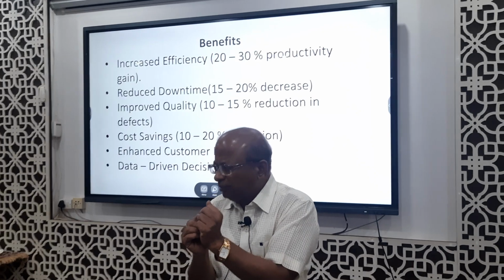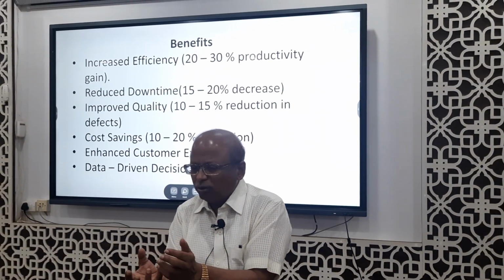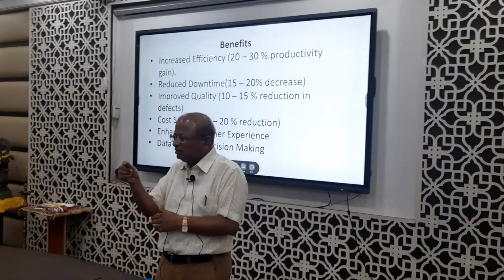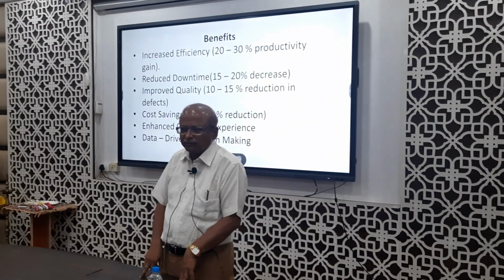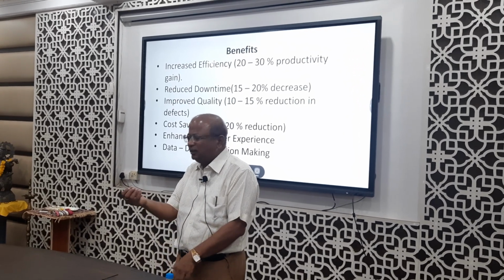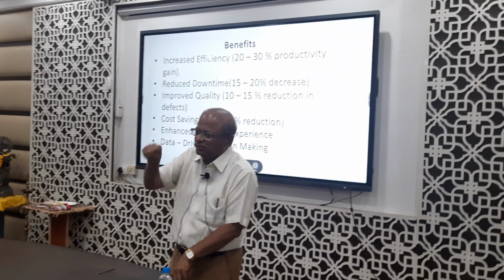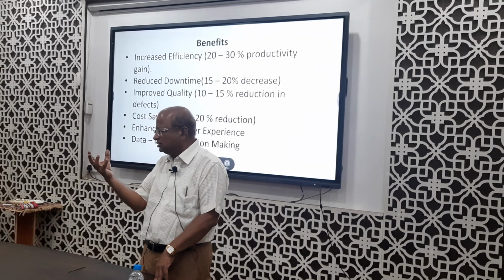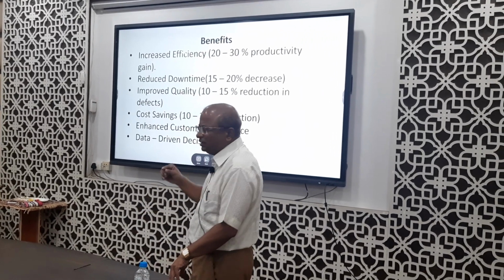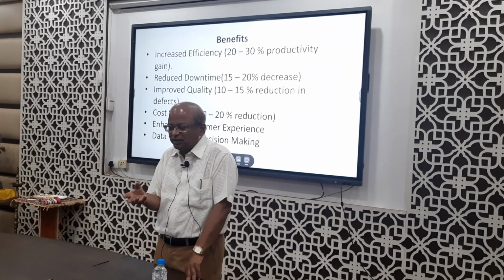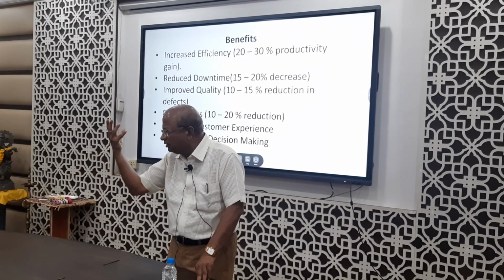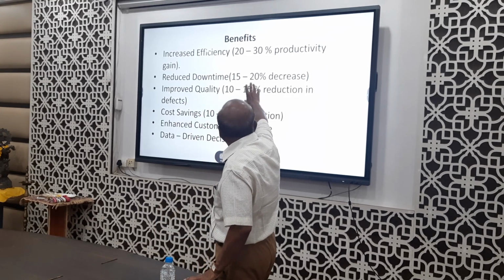With the help of this 3D printing machine, it is possible to reduce the weight of the drone, because with a single material, a single piece, the entire structure can be made without making use of nuts and bolts. So the weight of these nuts and bolts and screws etc. is reduced or eliminated, and therefore payload capacity is increased. And as I told, in a drone system, weight has a very important role. That is one example which I have given, of how this smart manufacturing 3D printing machine can contribute. It can reduce the weight of the drone, and therefore the payload capacity of the drone can be increased. Similarly, in various other places also, this was one example.